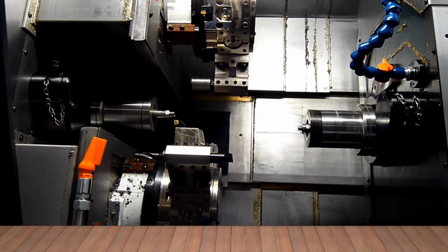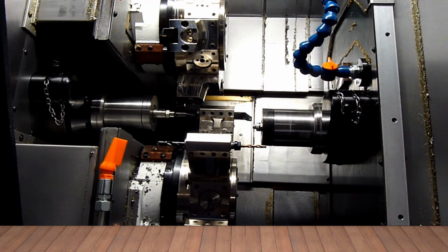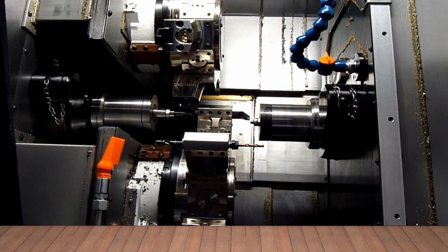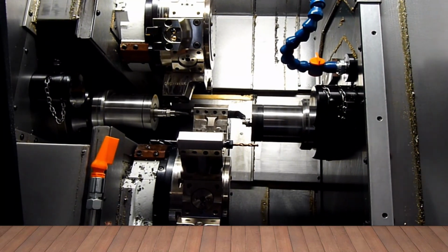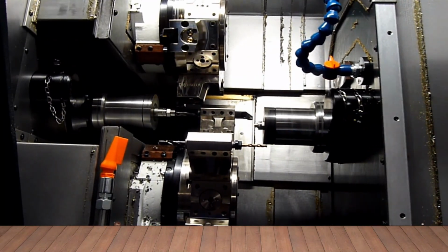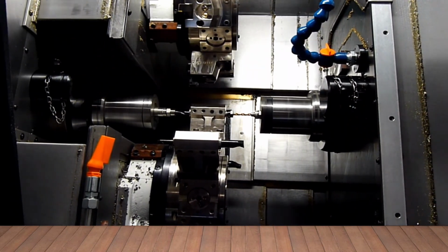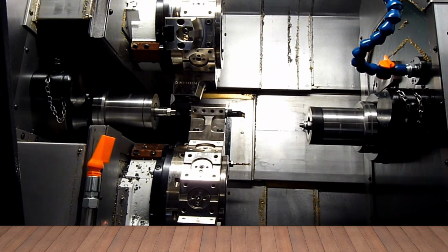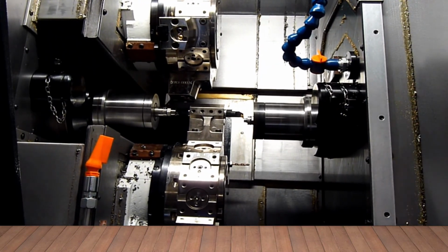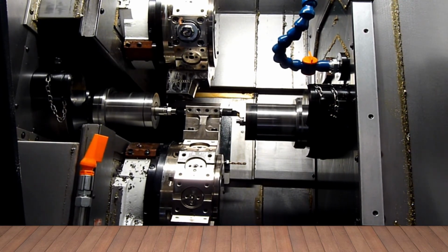Okay, here we go. Let's look at some superimposition in action. We did a face-off. We have a drill, and on the back side we're doing a rough turning, and on the upper turn we're doing a turning. Now we have a drilling on the main, drilling on the sub at the same time, and then a finish turning operation on the upper. All right, you can follow it along there.